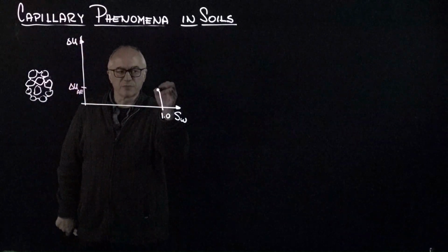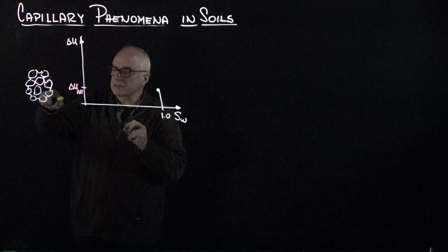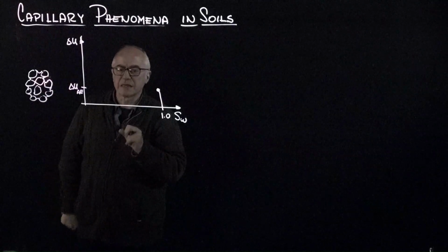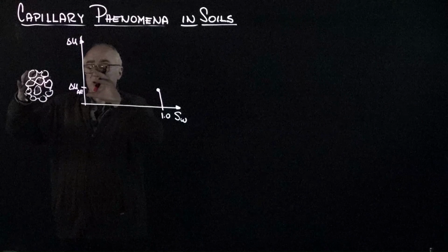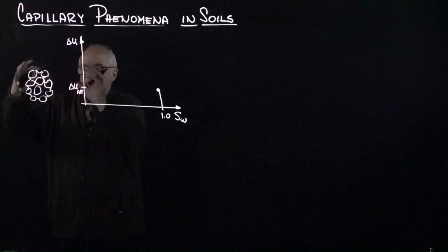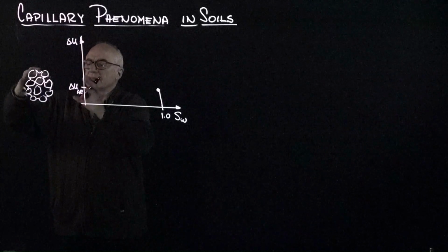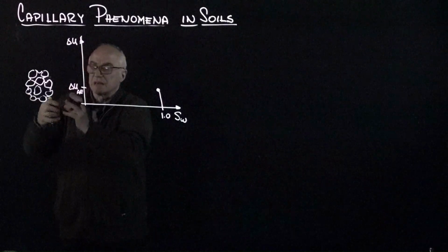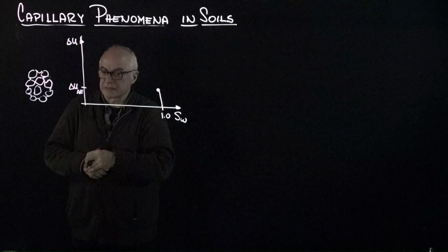That is a very important point, and it's going to be controlled by the largest exposed pore in the soil, because that is where the interface will enter first. Thereafter, the system will continue drying, and menisci will continue invading, reflecting which is the largest pore that comes next, and the weight of water in the soil is decreasing, while the degree of saturation is decreasing as well.